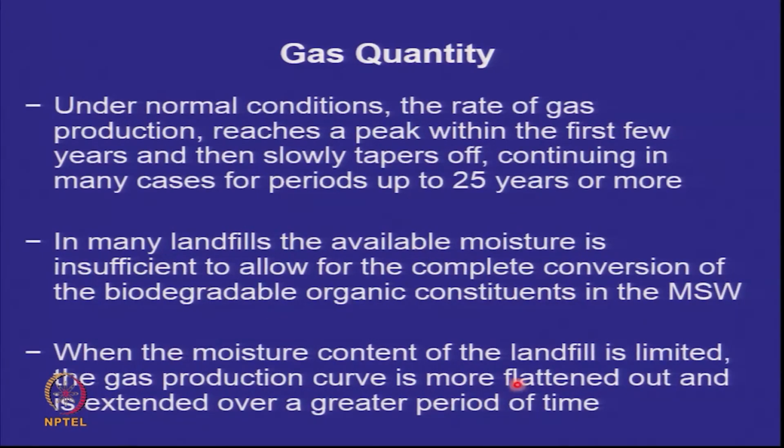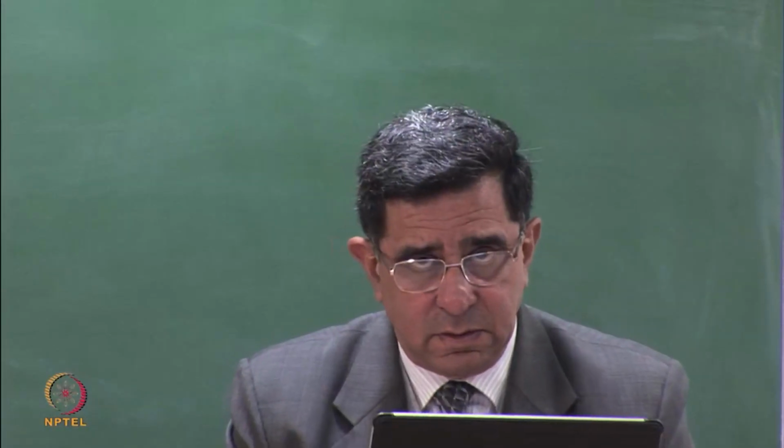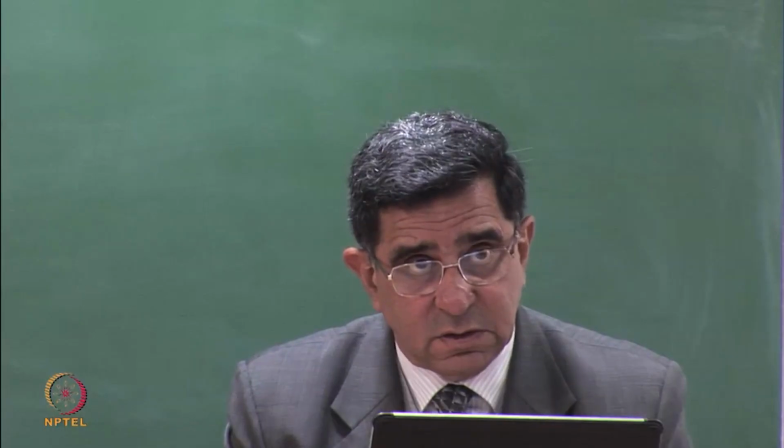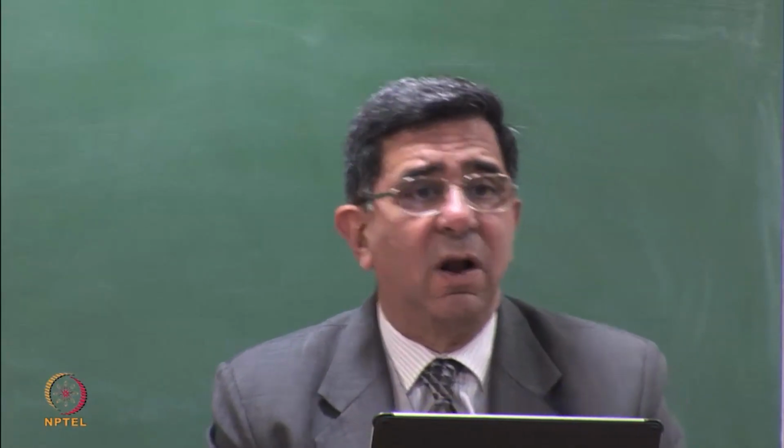When moisture content is limited, gas production is more flattened out. When moisture content is high, the gas peaks up earlier. So if I look at literature, because there are a lot of models which exist for gas generation, which model has anybody been following for landfill gas generation? Mohit, have you done anything about landfill gas generation?